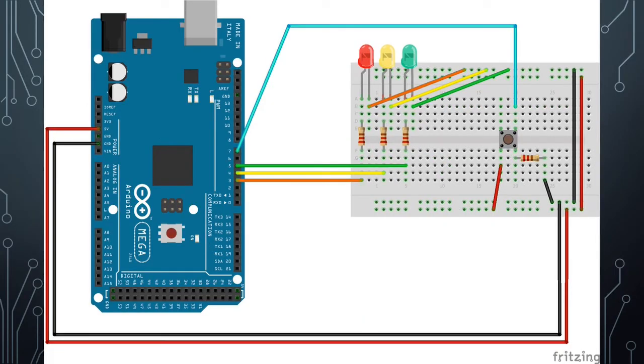And so this is just another diagram of another different way to set things up. On this board, we have a single push button, of course, top right corner connected to the pin that we'll use to read the status. Bottom left is connected to the power source, and bottom right with a resistor in between is connected to ground. And then we see we have 3 LEDs on the board.